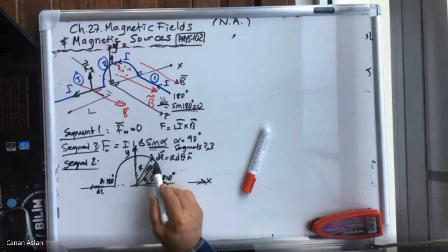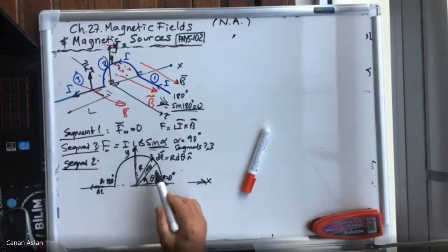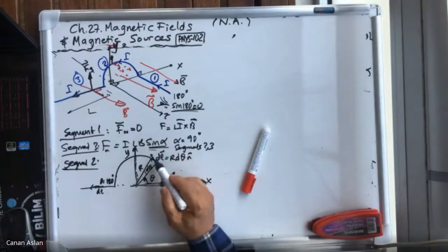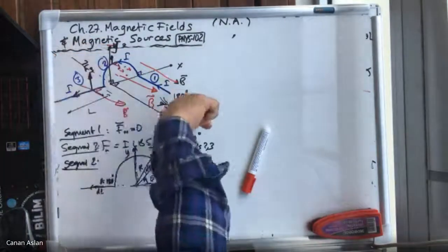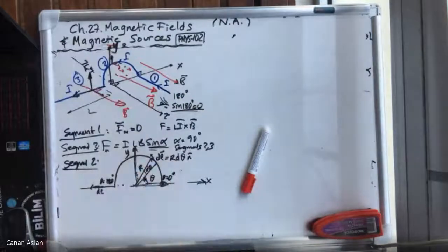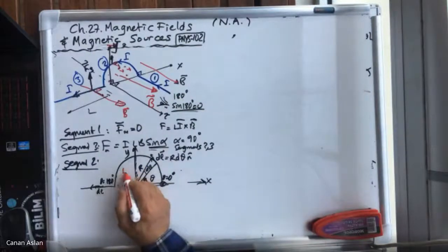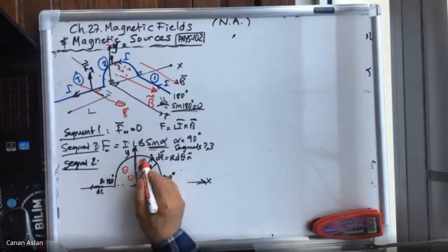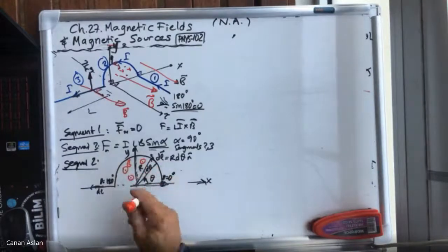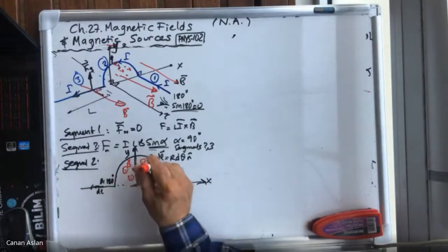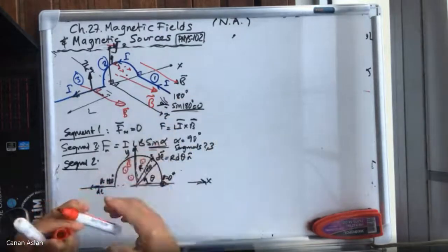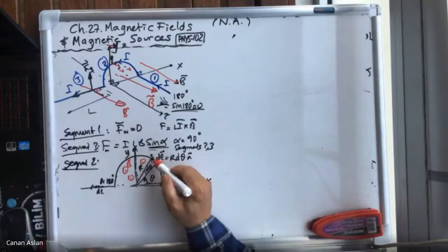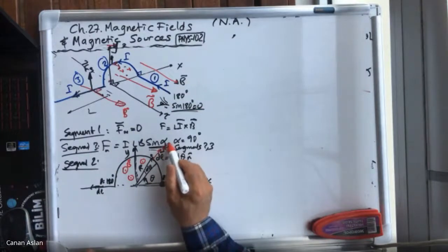Okay, so we would like to see the effect of this. What about the magnetic field distribution here? As you see, the magnetic field is now passing through upper direction, so it's outside the page now, the magnetic field line. The magnetic field lines are now going up like that. So if the magnetic field line is going up and the current is going down, the force is just the other way. So for this segment, the force will be like that, and it will be called dF.